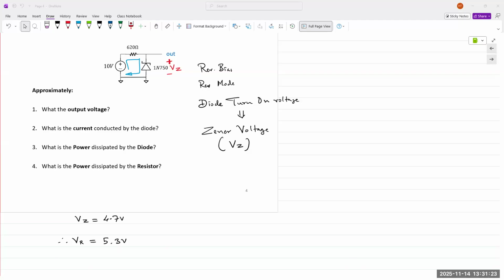Okay. So here's a special thing though. In a regular diode, let's say if we connected it in forward bias, turns on after 0.6, 0.7 volts, right? What happens if you increase the supply voltage? Let's say we are applying 10 volts, diode turns on at 0.7. What happens? Let's say we start at 0 volt supply voltage. Diode is off, circuit's off, everything is off.